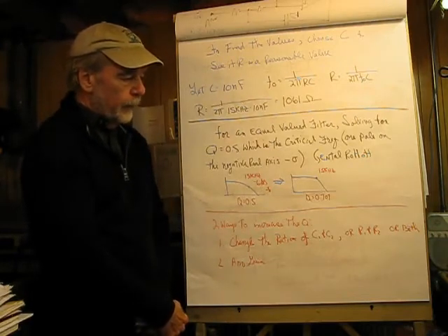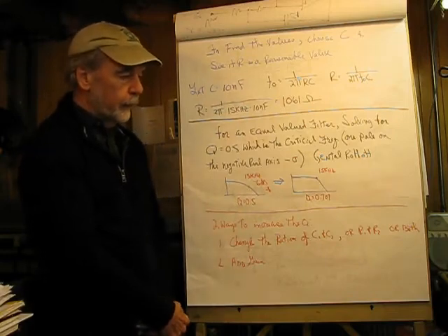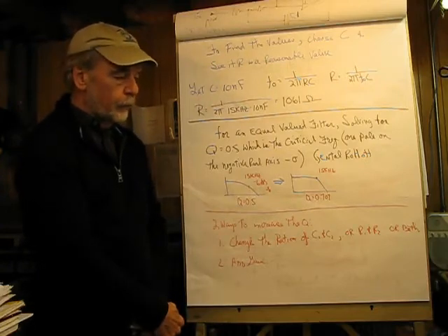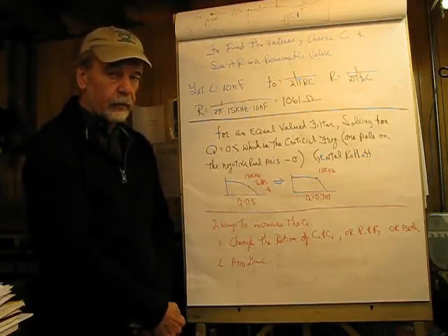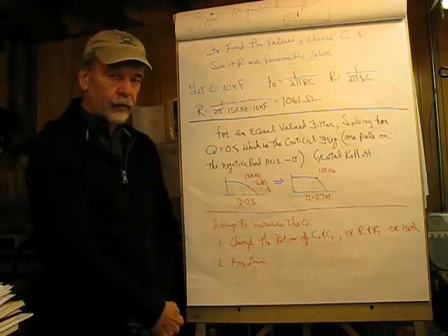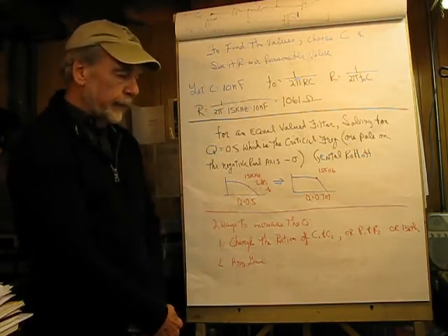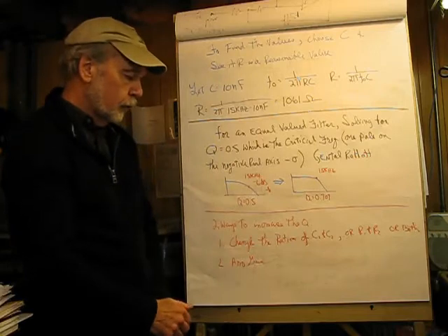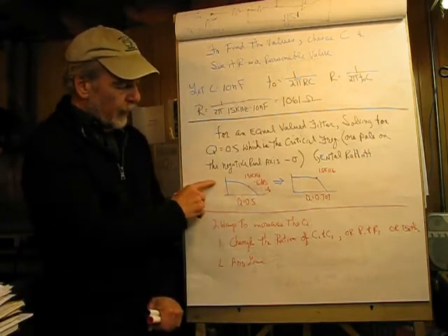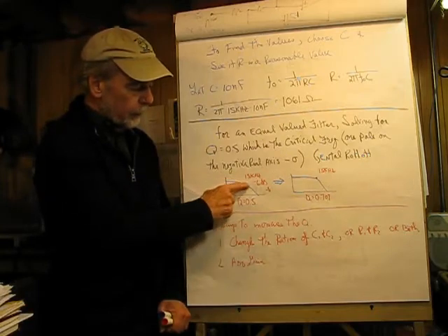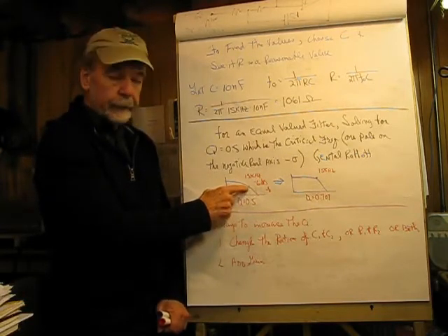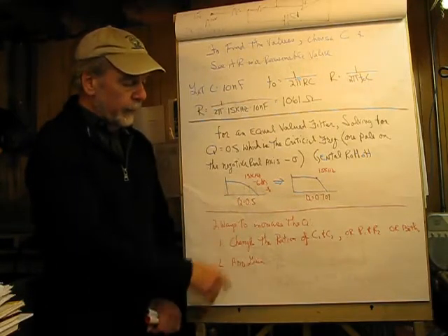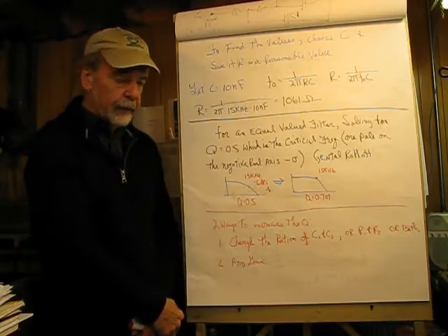Anything other than that is going to have two poles, and if the Q is less than 0.5, the two poles are going to be on the negative real axis, and if it's greater than 0.5, then they're going to be complex conjugates and have a component in the plus and minus j omega axis, and that'll give us some different characteristics not only for our frequency response but for our phase response also. If we have a Q of 0.5, the response would look something like this. The actual critical frequency, which is defined by F sub 0, is found to be about 6 dB down. It ultimately achieves negative 40 dB per decade.